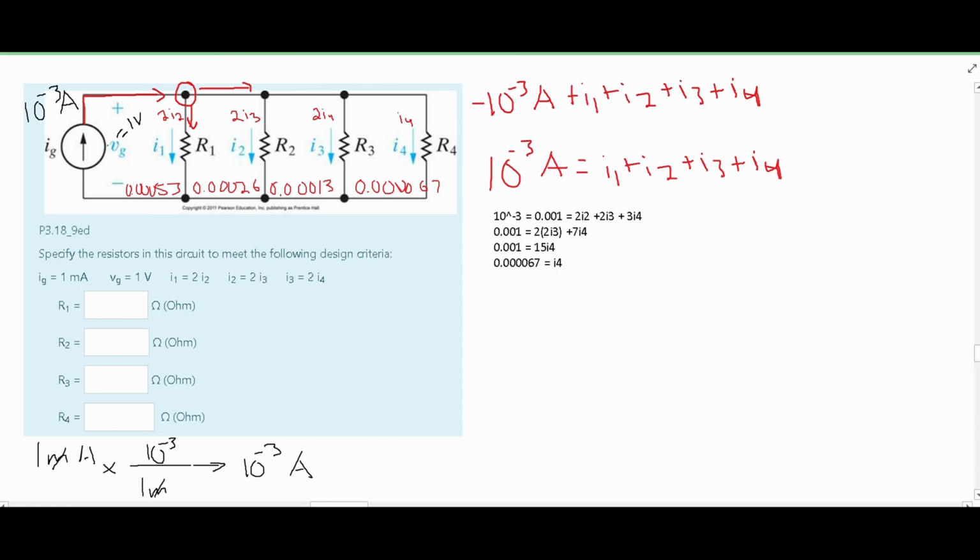Now all you have to do, since we have this voltage right here, and voltage is the same across a parallel circuit, is just plug this into our formulas for our R1, R2, R3, and R4. We know that we have the equation voltage is equal to current times resistance. All we have to do is modify this so we get voltage over our current is equal to resistance, and that is how we find our resistance. To find the first resistance, we're going to take our R1 and set it equal to the voltage divided by our current I1. If we do this but include more of the actual 3's, because this is just a rounded answer, we are going to get